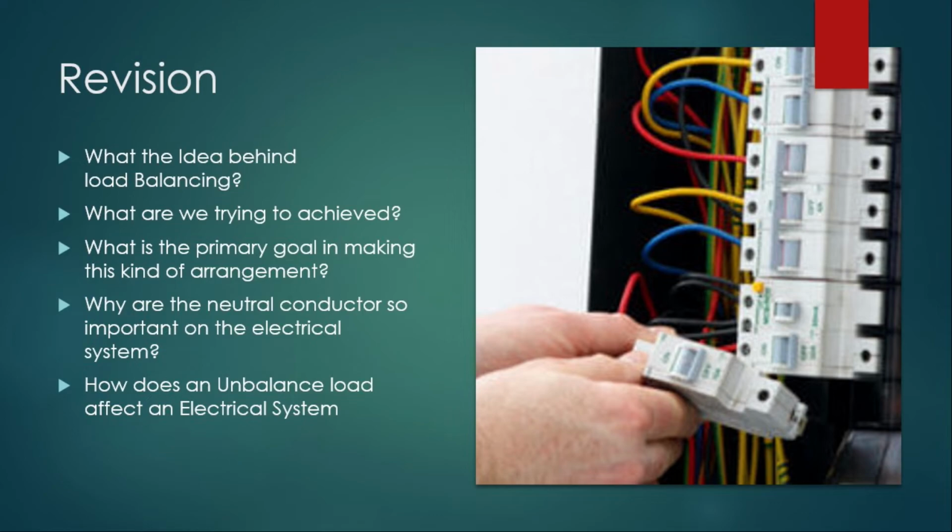is that we do so in a way that the return or the distribution does not create a hazardous situation. Because when we terminate our conductors incorrectly, it may add up more to the value of the return that comes back on our neutral. So we don't want that value to be exorbitant, such that the neutral would not be able to manage the magnitude of the current coming back on it.